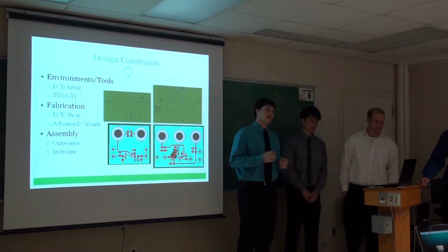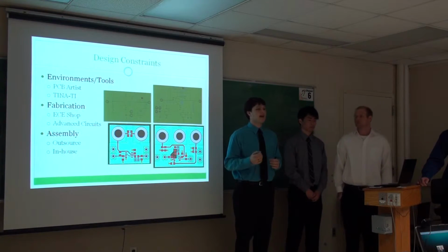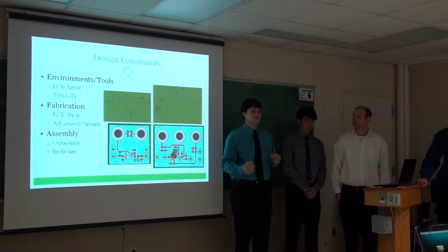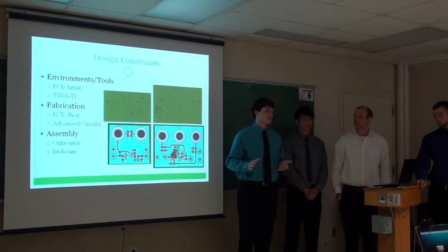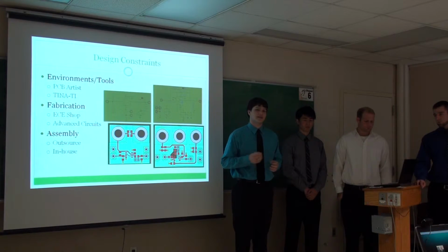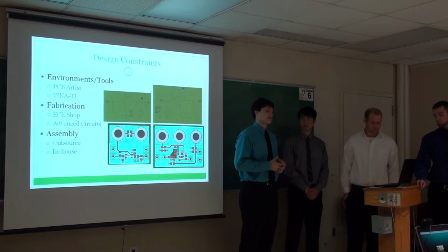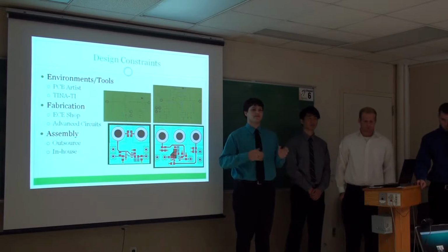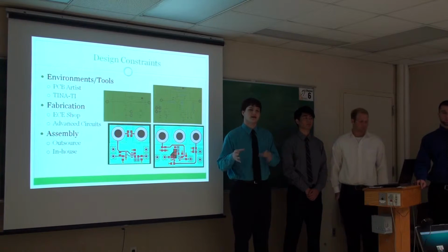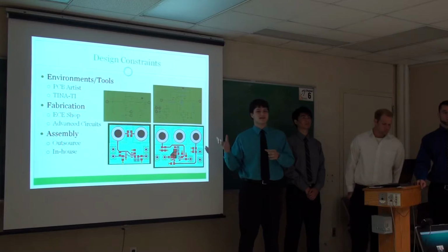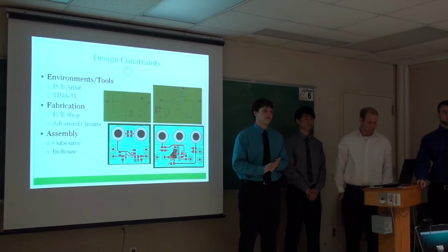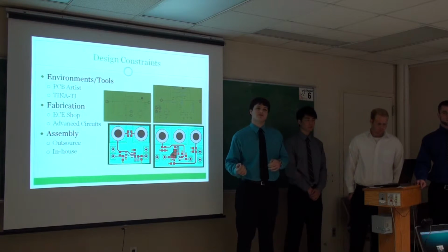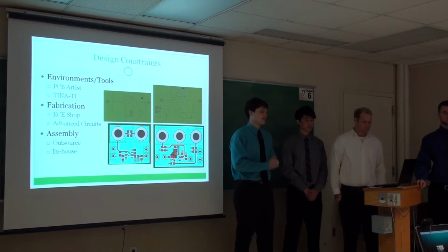The other tool that we'll have to be using is Tina TI. Tina TI is a SPICE-based simulation software that Texas Instruments has created. It's another piece of free software. This software includes all of TI's library and all of their chips that they've designed and their electrical characteristics. This means that when we are doing our SPICE simulation, instead of just having resistors and capacitors and defining those types of constraints, we have all of Texas Instruments' library. So when we have the INA333, the simulation software knows exactly how it's going to react to all of these different inputs because TI has already created this library for us.